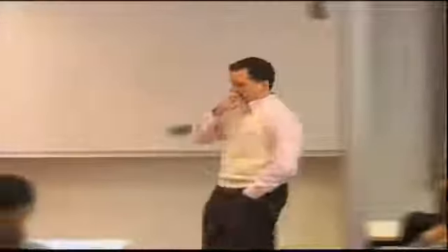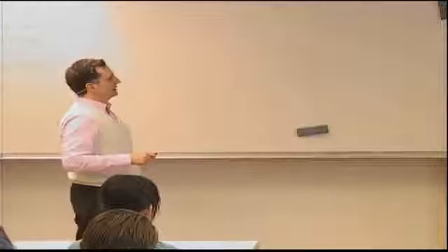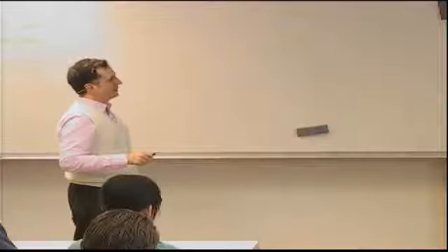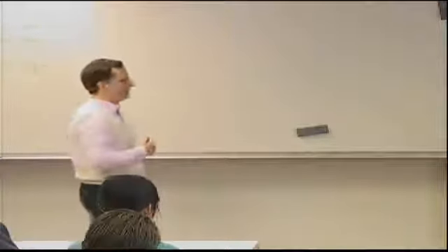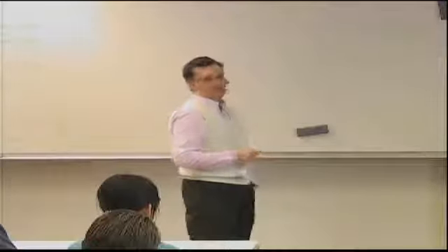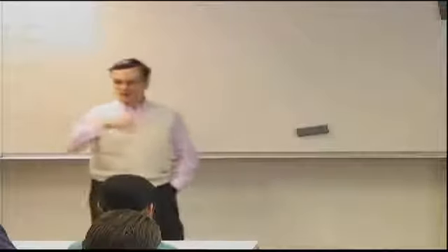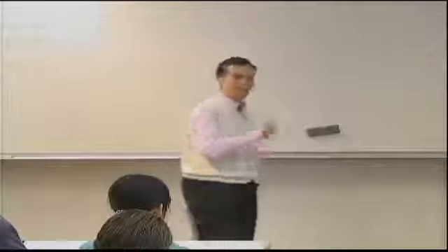So first I need to calculate my neutral axis, and because the two members have the same layup, they have the same E, which means when I calculate my neutral axis, each term would have an E there because it's the summation of the EA divided by the summation of the areas. But these E's being the same would cancel out, so I'm skipping an extra step.